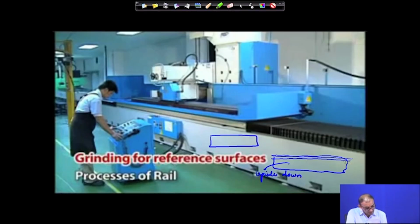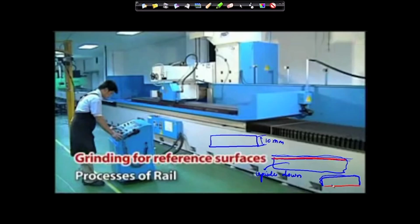Now we have created this reference surface. So, all the dimensions you want to machine, suppose it is 10 millimeters, then the 10 millimeters will be counted from that location. So, now this is your reference surface, and you have reached this location. Now, mount it upside down. So, now your surface is something like this. Let the top surface again be very uneven, but your bottom surface is completely flat, because you have taken it as the reference surface.